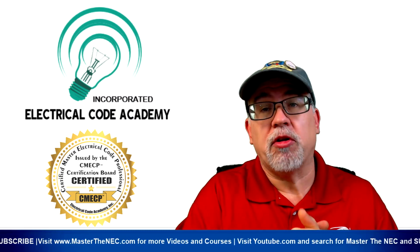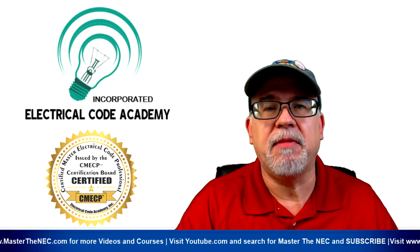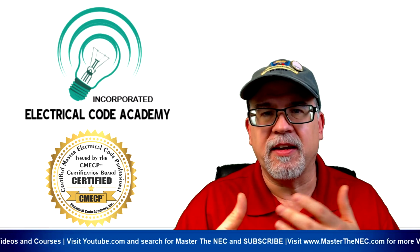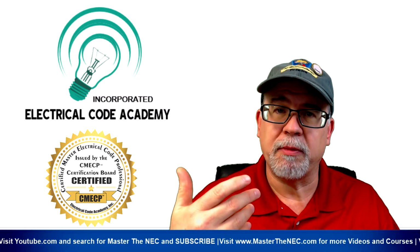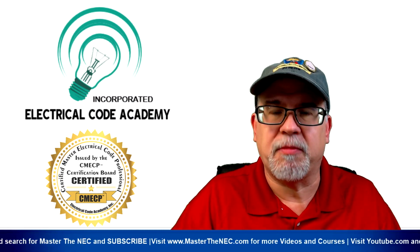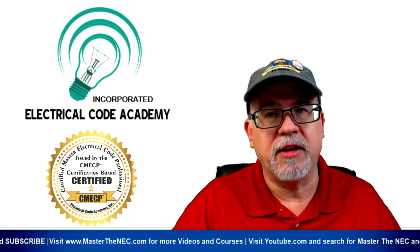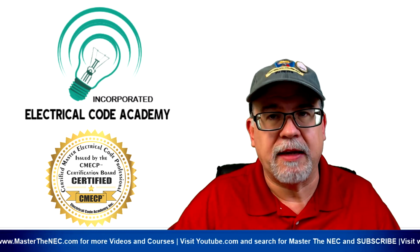Now, if you don't know how to do that, then you need to listen or watch our video, Derating Demystified. That's available on our website as well as on our YouTube channel. It goes over all the deratings and adjustments and corrections, dealing with ambient or the adjustment for the number of current carrying conductors. That's a real important thing. Just because I can put this many conductors in a raceway doesn't mean that I'm going to get the usability out of those conductors at their ampacity value. It's important that we draw a distinction between those two things, okay?